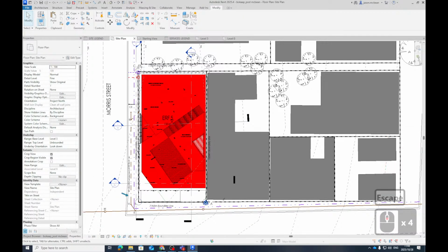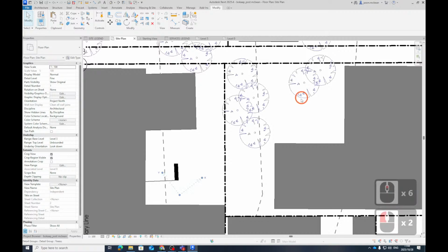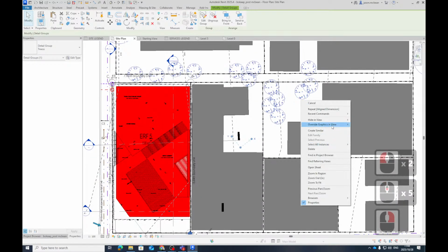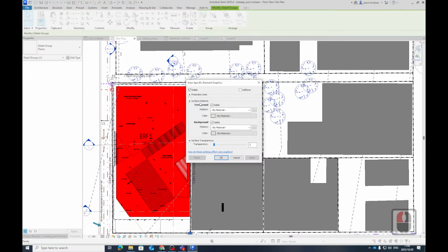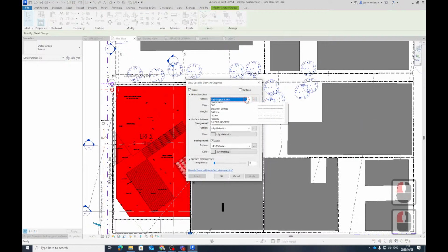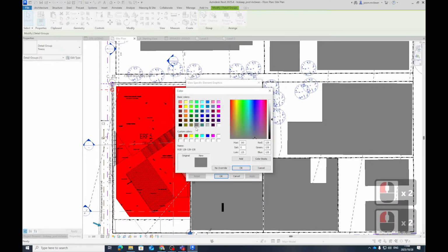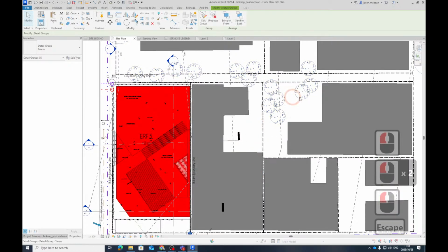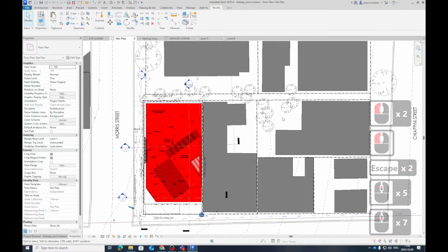Thanks. Very nice. Just the trees are also grayed out as well. If they're all in one family, you can also override them in the view by element. You can override all of these. Color, I just make them grayed out a bit. Make sure it's line weight 1 or 2. Apply. You see they're nice and grayed out and thin, and in the background, way better.